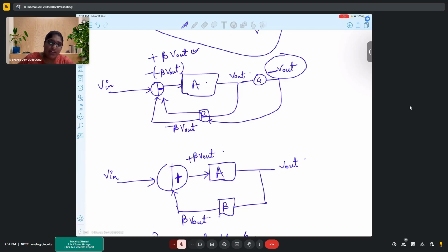No, I don't want to name it that casually, because looking at the circuit, it's not that straightforward. There is a transistor kind of device over there, which is more or less an inverter. Madam, we are very much confused about this. So that is what I'm saying. If I talk from a circuit's point of view, the circuit is basically an amplifier followed by an inverter, and then that inverter's output is being fed to your amplifier again.